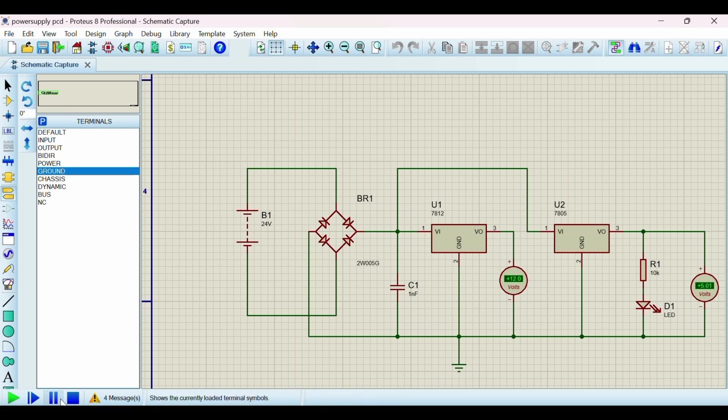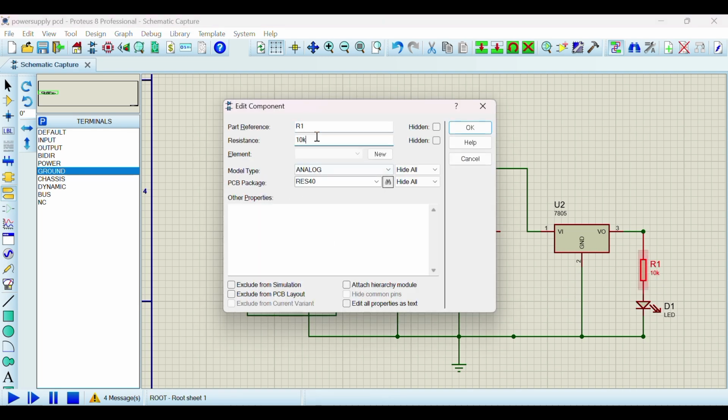And then next, here everything is okay, but the LED does not glow, so we have to change the LED, and we have to remove both DC voltmeters and the battery also. We have to keep the T blocks in place of the battery and the DC voltmeter. The resistor should be 180 ohms. We already know about that.